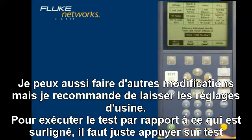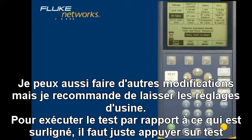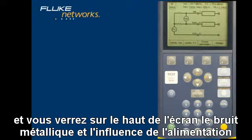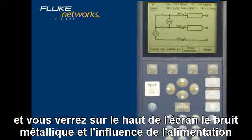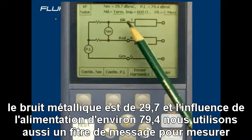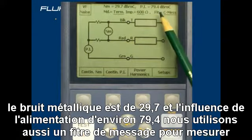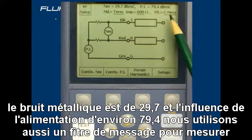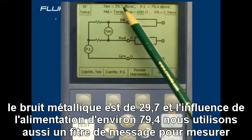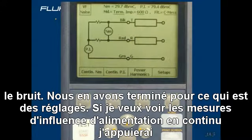To run the test, after we have it highlighted, we simply hit test. And you'll see in the top it displays the metallic noise and the power influence. The metallic noise is about 29.7, the power influence is about 79.4. We're also using a C-message filter to measure the noise, and we are terminated as far as our impedance goes.